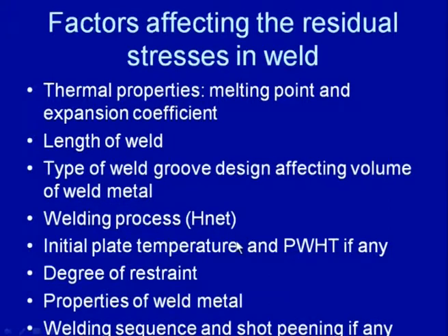Increase in initial plate temperature in general reduces the temperature gradient from the weld center to the base plate, and because of this, the extent of the differential expansion and contraction will be reduced. Similarly, if post weld heat treatment like annealing, normalizing or stress relieving is carried out, then this will help in relieving the residual stresses that are being developed.